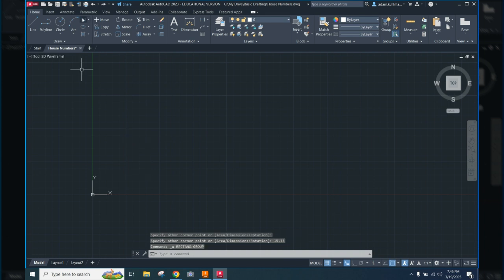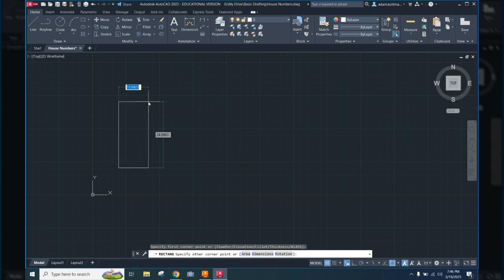Those two numbers that I typed in are each 1/4 inch less than 6 and 1/4 inch less than 16 inches. And the reason we're doing that is so we can maximize the amount of these we can cut out of a 48 by 48 inch sheet of material, which is the biggest piece of material we can put onto our plasma cutter.